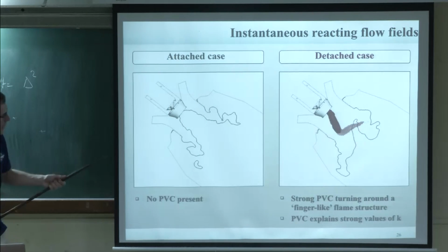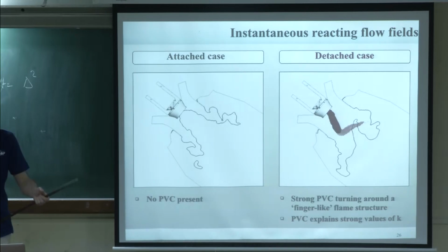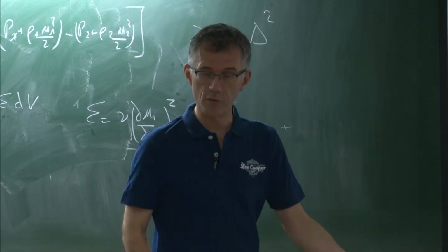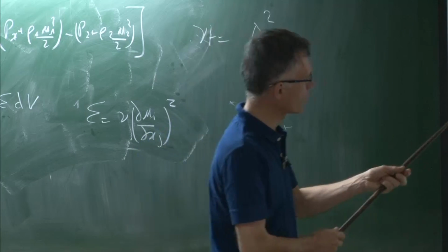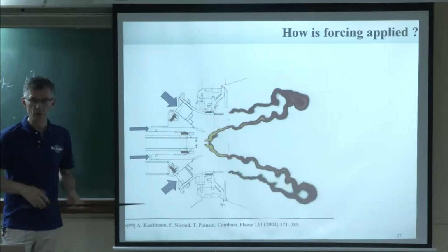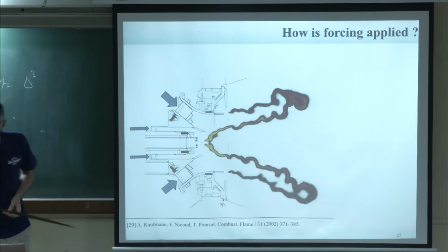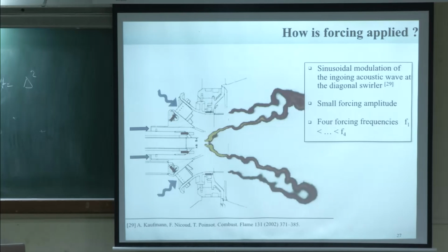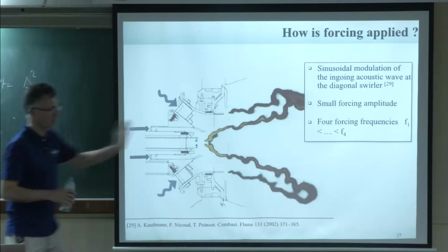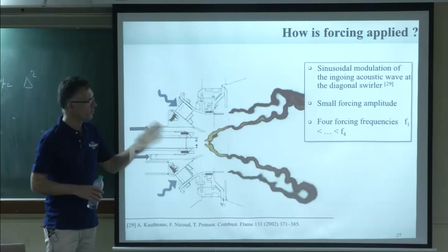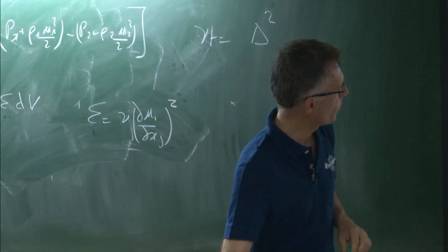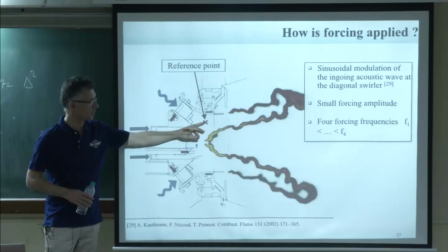When we'd done that, the first thing we did, because this was really a study on thermoacoustics, was to measure the flame transfer functions of these two flames. We sent acoustic waves here, using the methodology I have described before, and we did a few frequencies. When you do such a big gas turbine, you do them one by one. You force at frequency F1, you measure, then you do F2, and we did 4 frequencies like this. The reference point where we use the velocity is this one.